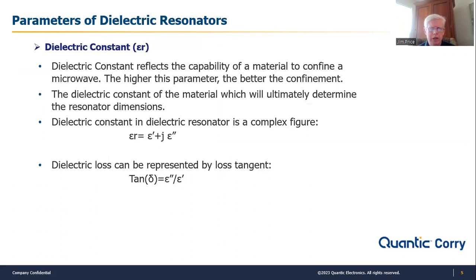Yeah, so in the example I just showed with the comb filter, those rods are in a vacuum. They resonate against the permittivity of space, which is by convention called one. These dielectric resonators, their permittivity is much, much higher than the permittivity of space, many times higher, usually 30, 35 times, something like that, higher than space. Their relative permittivities are in the 30 to 35 range.